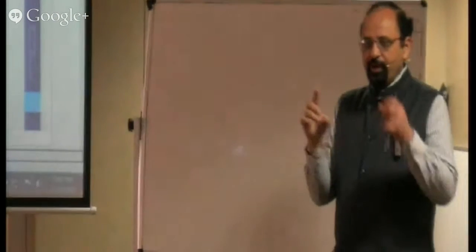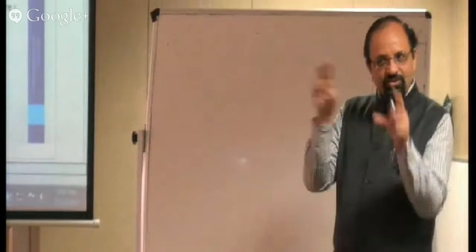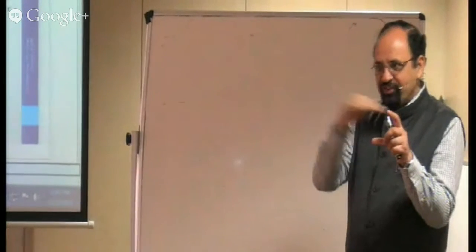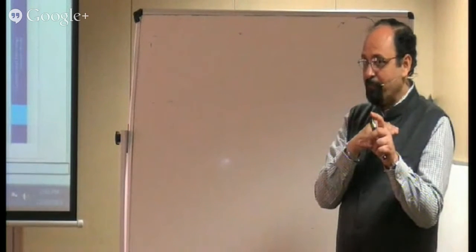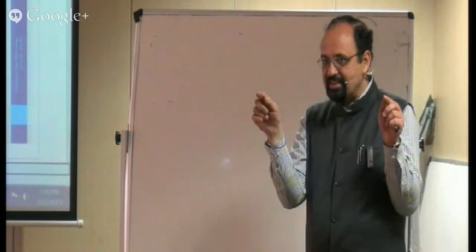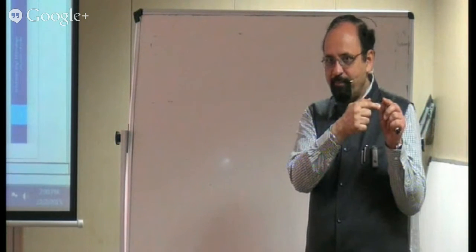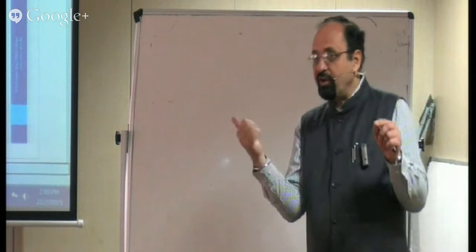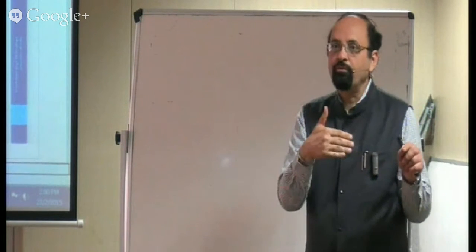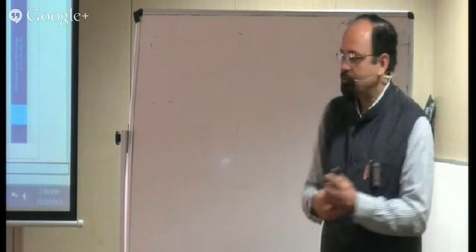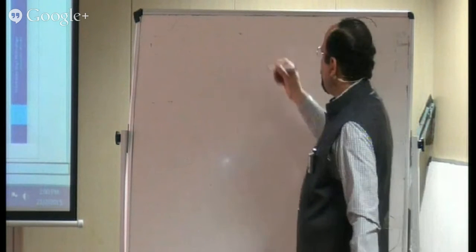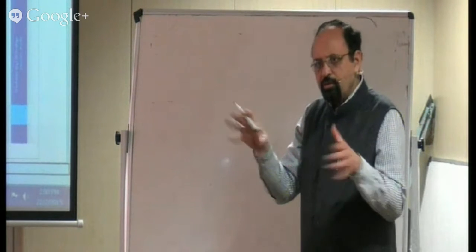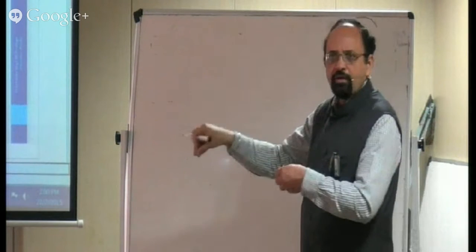Remember, I told you to have its analogy with the flow of charges, the electricity part. When resistors are in series, what remains same? That is current. And in our case, what is equivalent to current? Rate of flow. Q remains same. So I'll write one relation simply. I know the relation for Q. Don't write that. Write directly for the situation given.